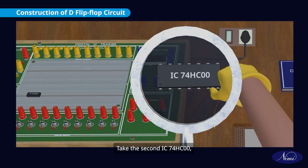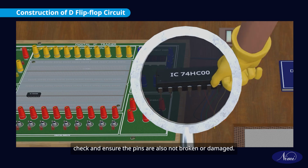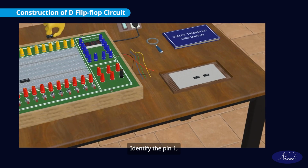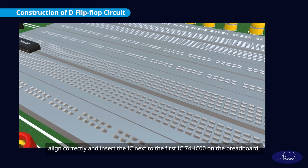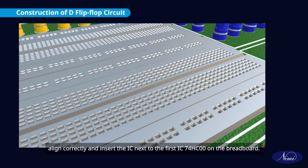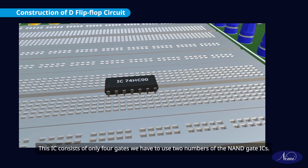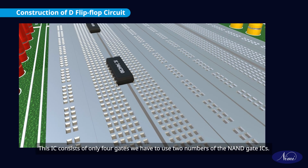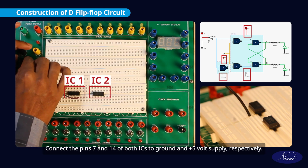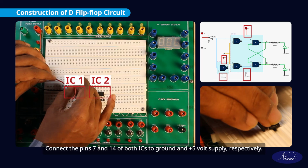Take the second IC74HC00, check and ensure the pins are also not broken or damaged. Identify the pin 1, align correctly and insert the IC next to the first IC74HC00 on the breadboard. This circuit requires 5 NAND gates. This IC consists of only 4 gates. We have to use two numbers of the NAND gate ICs. Connect the pins 7 and 14 of both ICs to ground and plus 5 volt supply respectively.